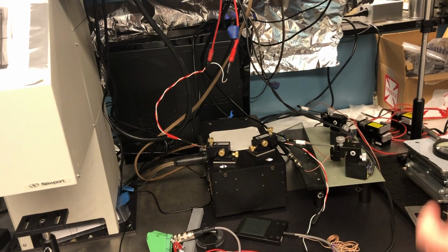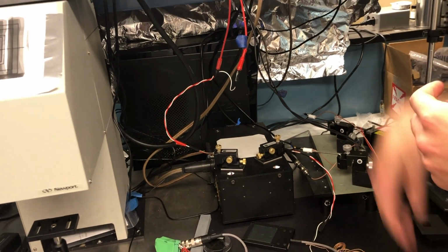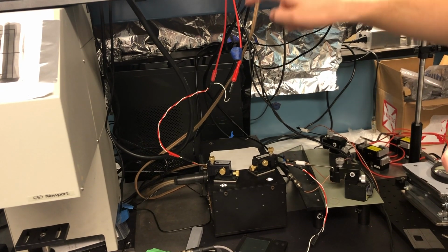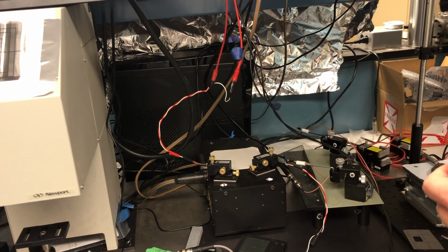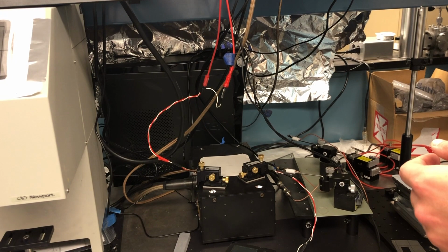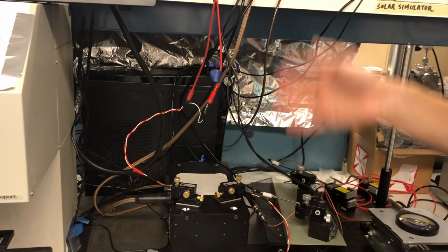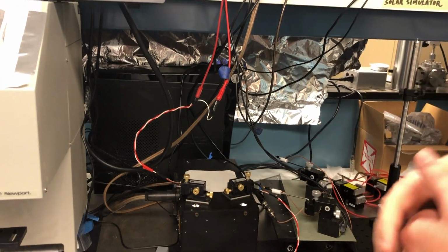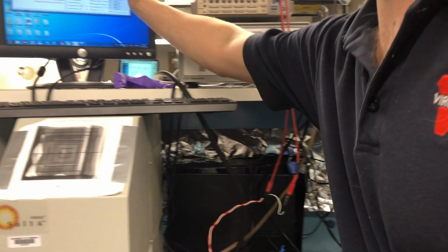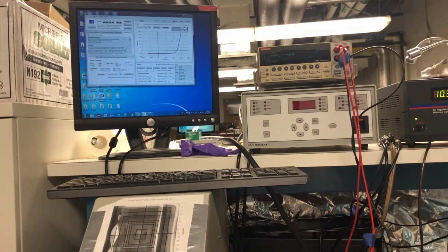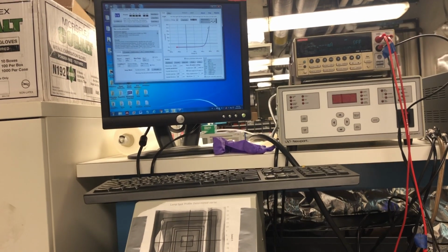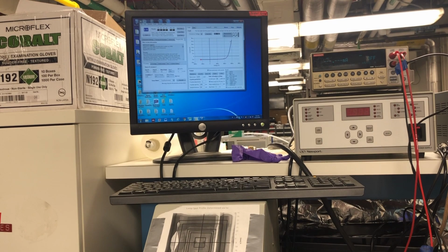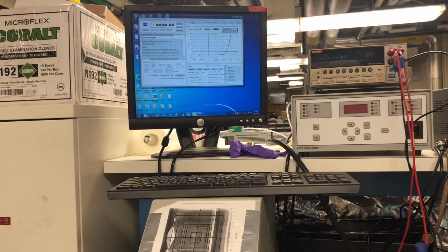Why is there 4? So if you just do a two-terminal measurement, there's resistance added from the leads. Oh, and if you're trying to get below 1 ohm, so can this one exclude the contact resistance? Yeah, you lose the contact resistance, you lose lead resistance, and you should see a lower series resistance as a result. So you'll get a sharper VOC slope. And that's standard practice to do that. They even argue about how closely probes should be spaced. They do like a multi-probe measurement at NREL.